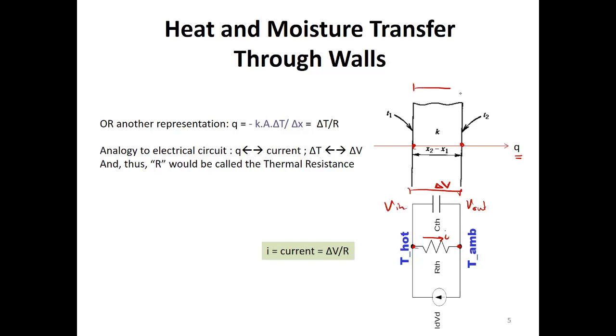The same goes here. You have a temperature difference between the two surfaces, so that's why you're going to have a heat transfer rate. Now, what controls this current I, the flow of the current I, or the flow of the heat transfer rate? It's the same. So I is determined by the value of delta V and the resistance R inside the medium that it's going through. The same goes with Q.